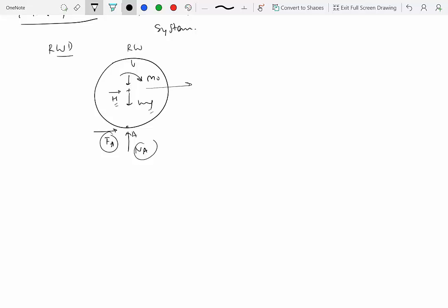So this may come as a surprise to you, but in this particular case, the friction force is actually not doing any work in making the wheel go in the forward direction, because under the rolling without slip condition, the point A actually has zero velocity. This point is actually not moving. So that means that there's no work done by F_A. And if math is what you like to see, exactly whether the work done by the friction force at A would be zero or not, you can see that.